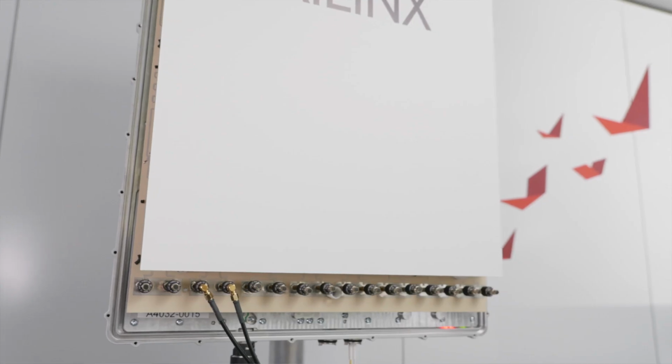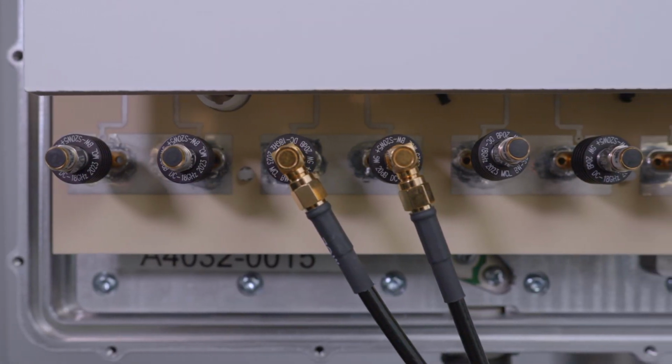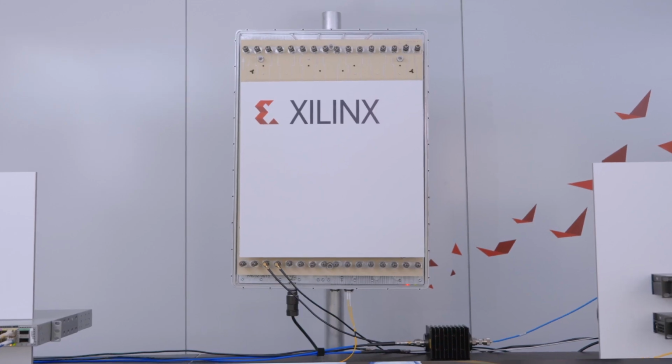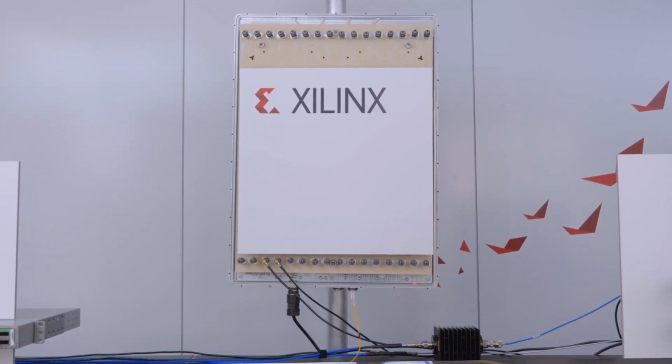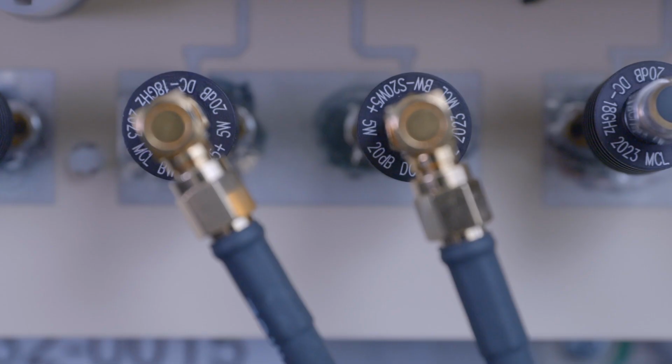Next, we have our RU, which in this case is a Xilinx reference design for a massive MIMO radio unit we call the Array 4032. It features 32 transceiver chains and runs the O-RAN, CUS and M-plane powered by 3 Xilinx RF SoC chips. As we're not in an anechoic chamber where we can radiate the RF signal, we have removed the radome and are using a cabled connection.